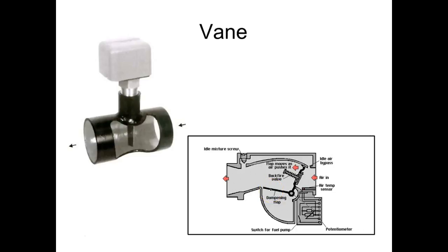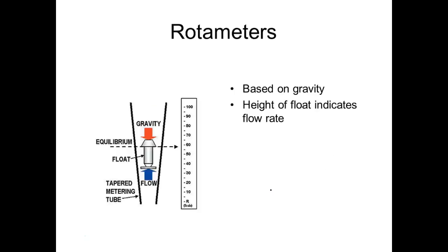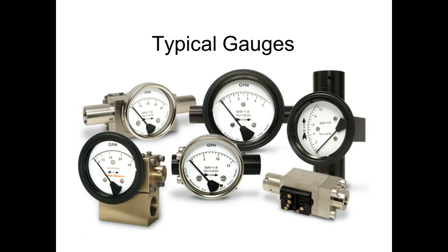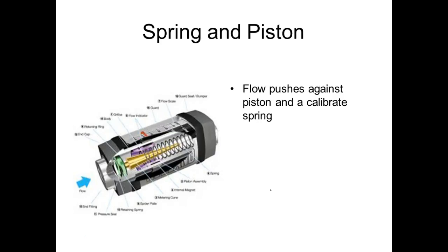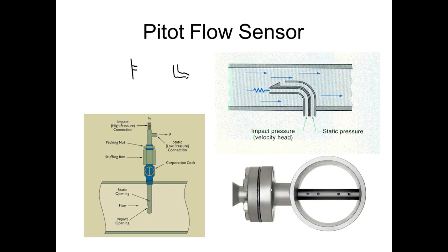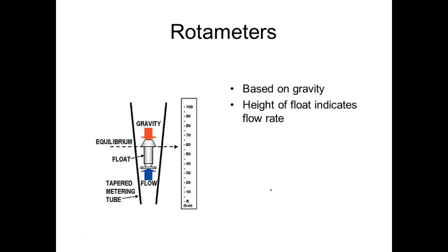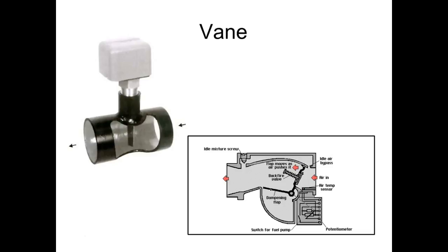A lot of fluids, when we're running with pumps, especially pneumatics and stuff like that, pneumatics or fluids can have a fluctuation to it. And of course, that's why on a lot of our meters, I don't know if we can see them on these meters, but a lot of your pressure meters have that gel inside of them to do what? To dampen it. And what it does, it takes out that fluctuation, which could be a lot of stress on your vane and everything. That vane was sitting there doing that, right? And it would be a lot of stress.